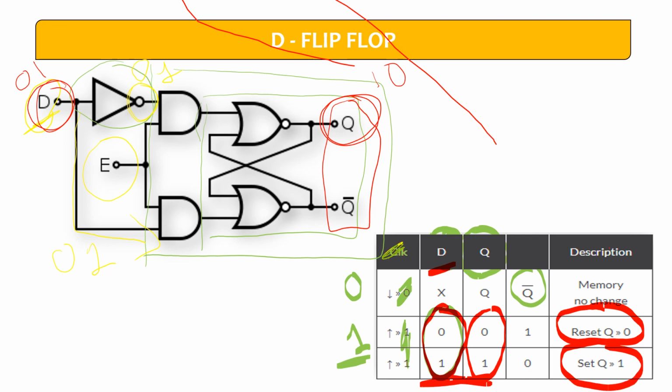This thing you can check by doing the same thing as in the first animated image, right? Just check what happens when you insert the 1, when you change the 0, because every time you have to check the status, like what you are inserting here, what you will get here, what you will get here, and what you will get here. And at the end, because all the outputs are going to be the input for the next cycle, you have to take care of all these things, right? So this is the simple idea of the D flip-flop.